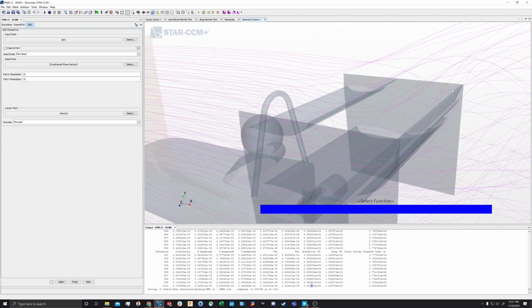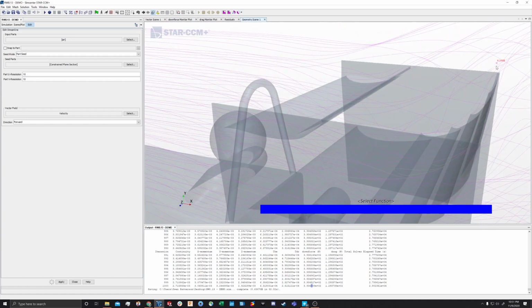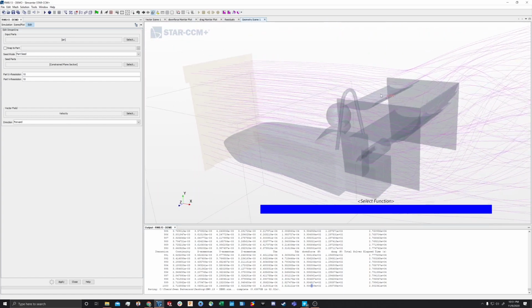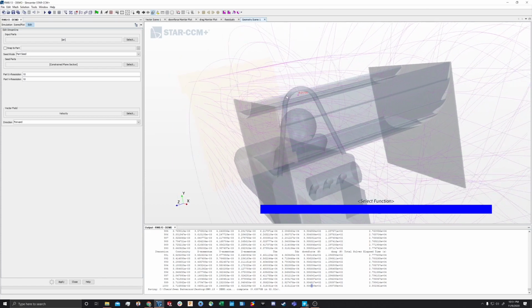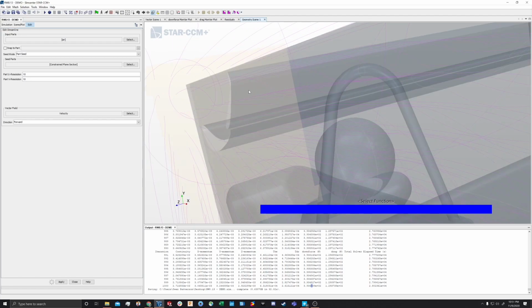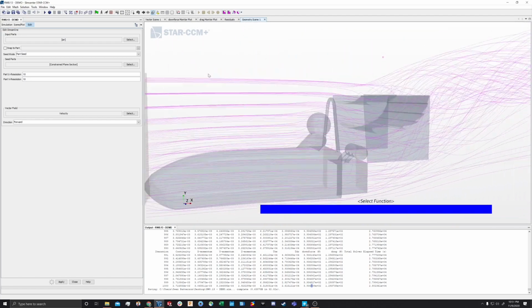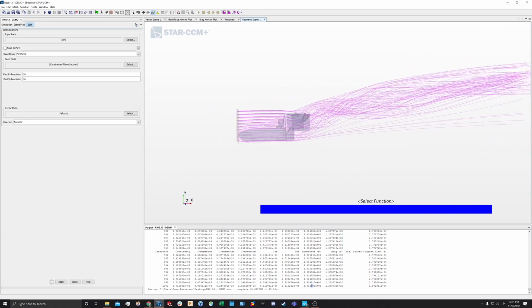And you've got streamlines of air moving up here through our spoilers on top of these wings. So there you can see we've actually got a really tight vortex right at the top of the end plate. The more streamlines you add here, the more precision you can get, but the harder it is to pick certain things out.